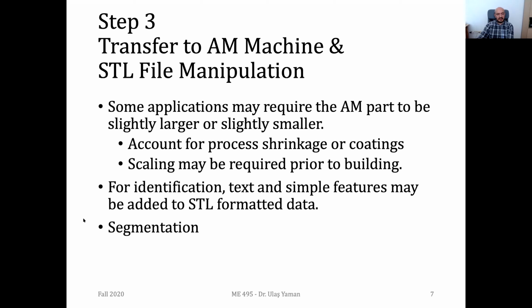Another thing you can do, if your design is a large one, but the build volume might be smaller, is divide your part into smaller segments in that CAD software. With the help of this approach, you can print them separately, and then later, once all the parts are printed, you can join them by using some glue-like things and have the final product.